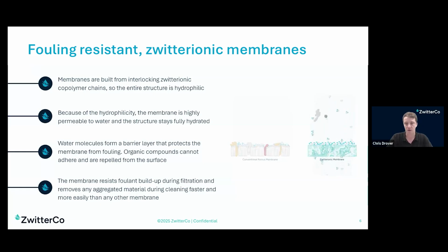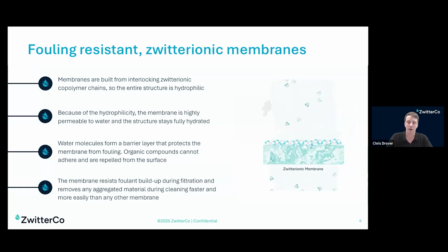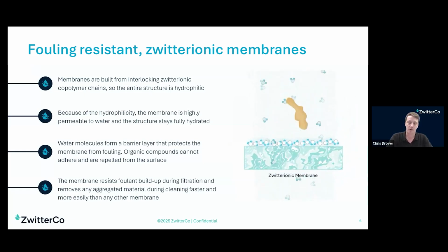Finally, the zwitterionic chemistry we use is overall charge neutral and has a bunch of other chemical properties. And we've engineered it so that's true over the entire operational pH and temperature range. So the membranes don't depend on a particular set of conditions to have their hydrophilic and anti-fouling properties.